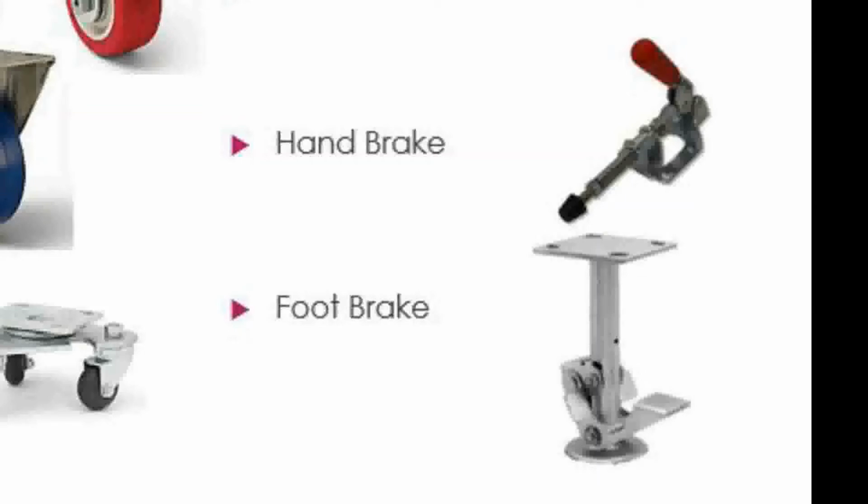These are meant to be set so that they lift the scenery a fraction of an inch off the floor, just enough to take weight slightly off of the casters so that they are not able to roll. Okay? They are not meant to lift the scenery off the casters completely. There are certain brakes that are designed to do that. These are not those. These are meant to provide a little bit of tension with the floor so that it's less likely to move.